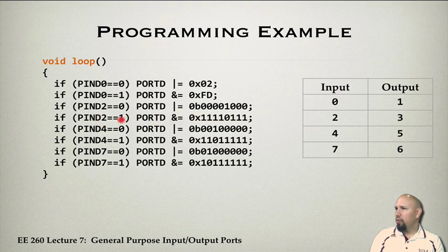So when pin 2 is equal to 1, pin 3 needs to be the OR of that, and so basically this is clearing pin 3. Okay, and so these two commands together basically set the output, which is on pin 3, to be the OR of what's happening in pin 2. Okay, can you see how that's happening? So this concept of using a mask is effective.